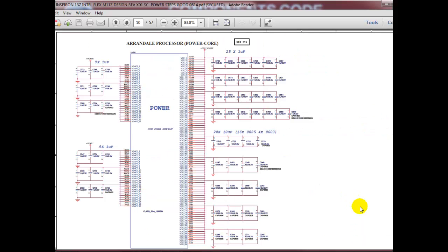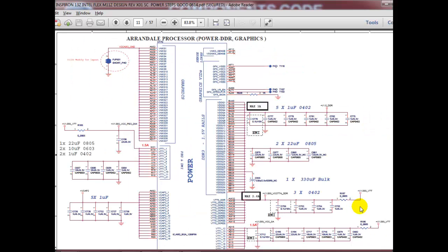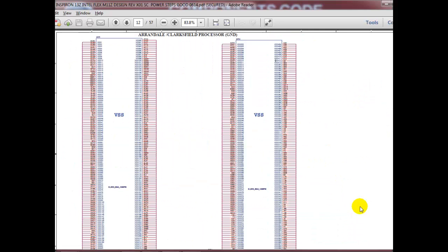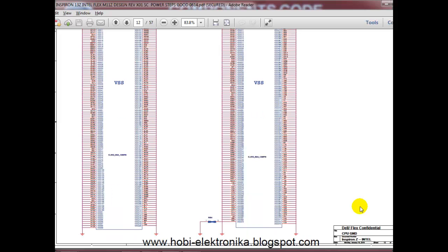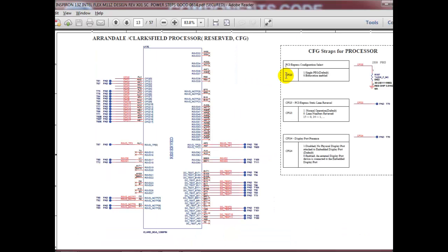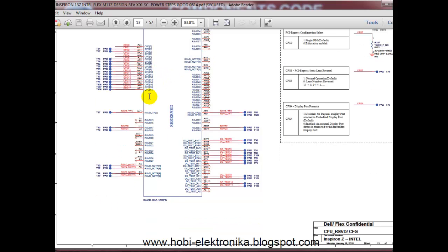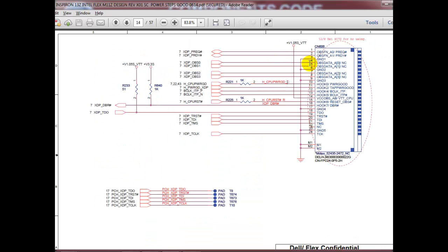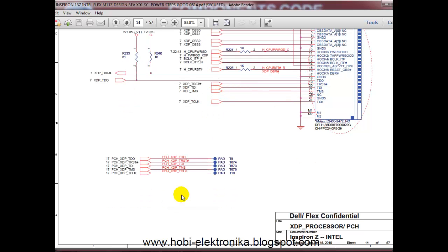We have already explained which connection means what, the symbols, and how to identify them. This is your ground pin, meaning all these pins are ground connected. Identify the pin numbers, like BT5, BT7. These are the pin details. Which leg it is, the pin numbers are here: 1, 2, 3, 4. It is send and receive. These symbols are here: this is inward, this is outward, and inward-outward, both kinds of signals.